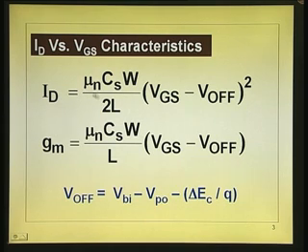So, what we have written is exactly the equation of the MOSFET, because the oxide is replaced with that depleted layer, and the channel inversion layer is replaced by the 2-dimensional electron gas. Mobility will be the mobility of this electron gas, which is high. Cs is actually epsilon r epsilon 0 by the thickness of that layer. Now, notice you would bargain for thinner layers. Why do you ask for a thinner layer? Cs will be larger. If Cs is larger, for a given change in voltage, the change in ID will be large, which would mean gm will be large.